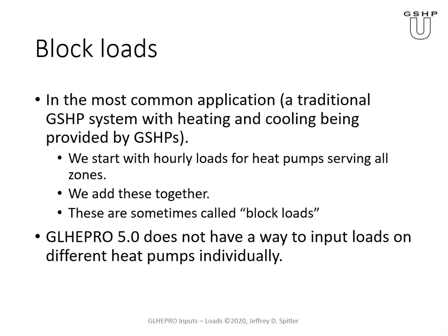The building simulation tool calculates the loads for each hour on each heat pump, and we get those loads out and we add those together, right? And we add the loads for all the heat pumps that will be served by the ground heat exchanger. So these are sometimes called block loads for the building.